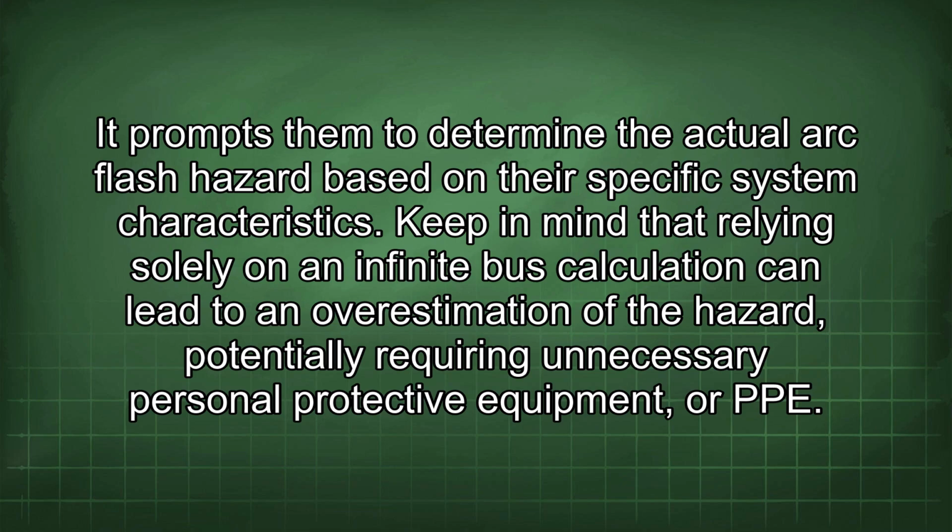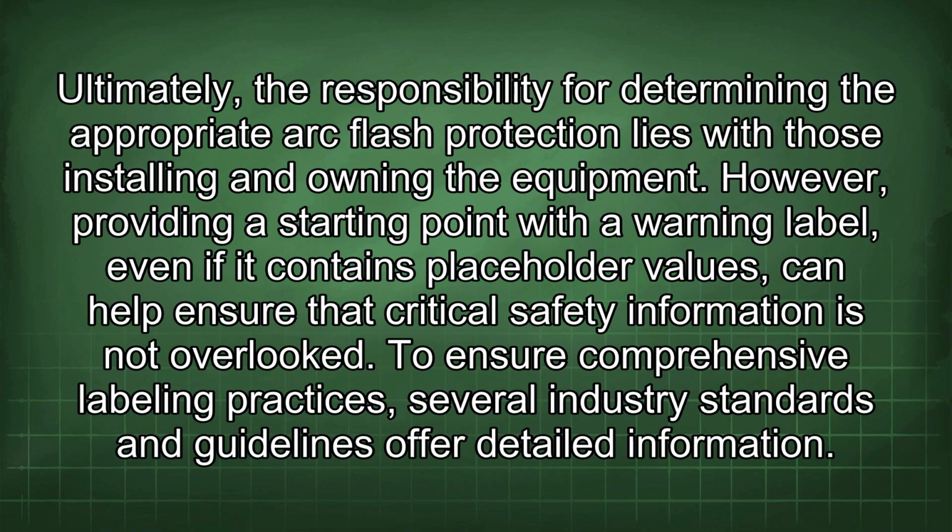Keep in mind that relying solely on an infinite bus calculation can lead to an overestimation of the hazard, potentially requiring unnecessary personal protective equipment, or PPE. Ultimately, the responsibility for determining the appropriate arc flash protection lies with those installing and owning the equipment. However, providing a starting point with a warning label, even if it contains placeholder values, can help ensure that critical safety information is not overlooked.